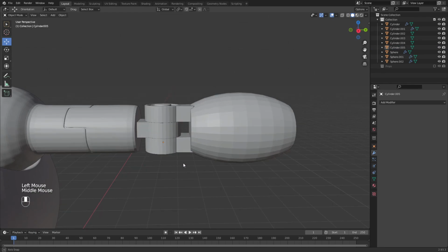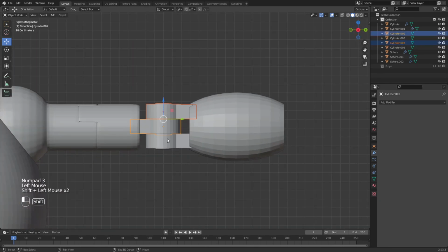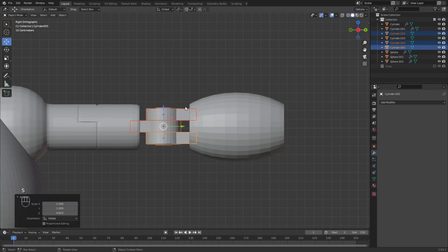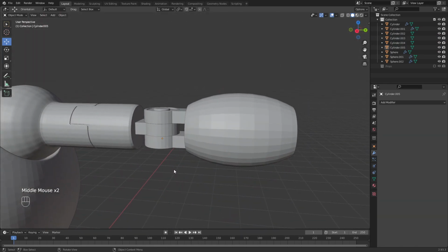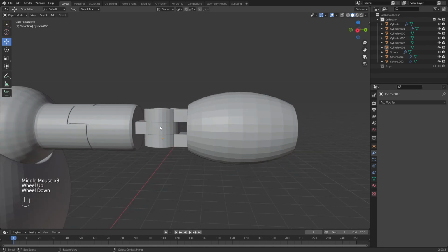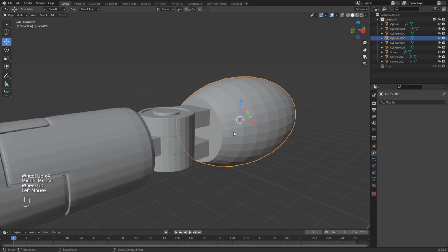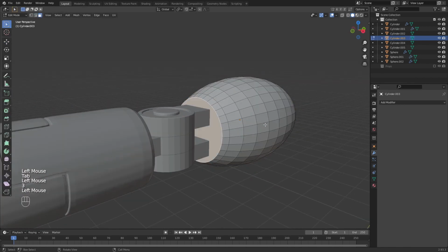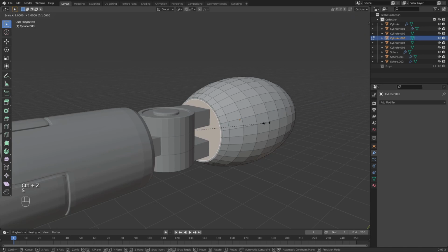And then I'm gonna duplicate it once more and place it on the underside of the middle joint. Then I'm gonna select all of them and just scale them down so it fits inside both of the arm joints. And yeah, that's basically your joint all done there. Now the joint looks good, but it's sticking into the arm and nothingness. So we should make a socket for the joints inside of both sides of the arms. To do that, go into edit mode while selecting the lower arm, and then select this face that's facing the joints, and then insert it and then extrude it inwards.